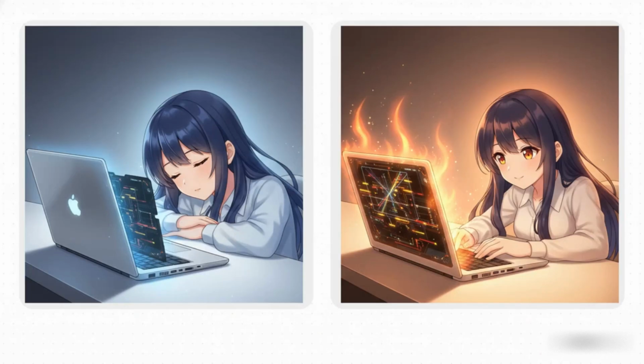When we talk about power in a chip, it really comes in two flavors. First, there's static power. That's the energy the chip leaks when it's just sitting there, doing nothing. And thanks to that amazing complementary design of CMOS, this is practically zero. It's incredible. But then, there's dynamic power. This is the energy you burn every single time you fill and empty one of those buckets. Every single switch from 0 to 1 and back again burns energy, and that is what generates heat.